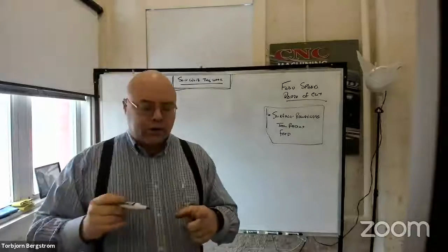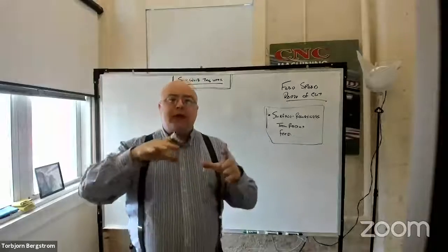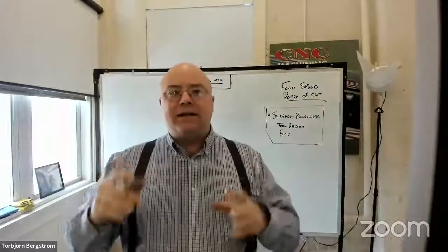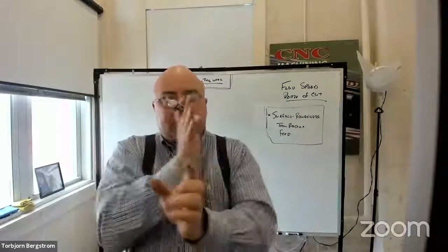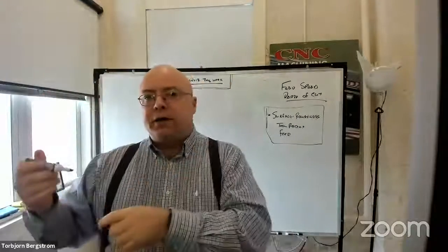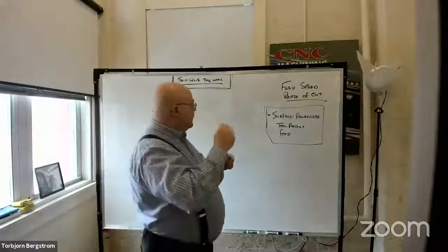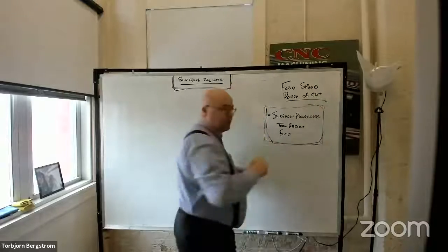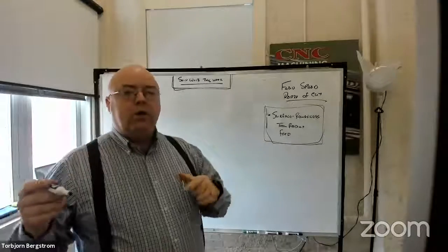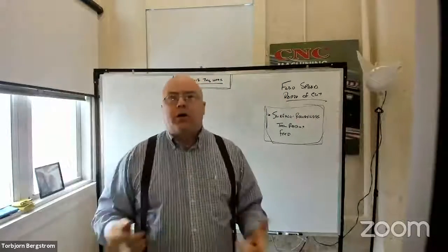What else do we know about our turning? Let's just focus on turning operations right now. But I will tell you right now that everything we learn and figure out for a turning operation is exactly the same in a milling operation as long as you get the axes oriented in the right direction. So the chip forming on the edge of a turning tool is the same as the chip forming on the edge of a milling tool. It's just they're not going the same direction relative to where the operator is standing. So what do we know from physics about our turning and cutting operations?